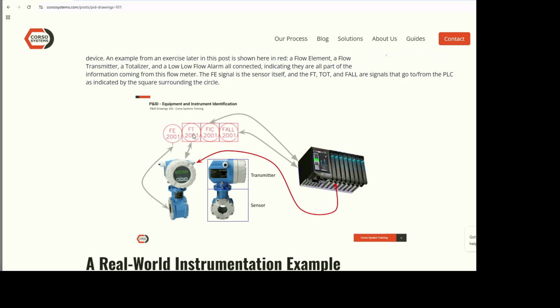And in this case, we would have a tag for our flow value, a tag for our alarm, and we may have a handful of tags for the controller, including a set point, a process variable, a control variable that we're sending to a valve or a pump, and maybe some other things like the proportional, integral, and derivative gain for that control, and any alarm conditions, if it's in auto or manual, etc. So just to read flow, you probably have at least one tag, if not a few, to include alarms. And then if you get into control, you would have additional tags for this flow sensor, and then whatever tags are required for your equipment that's controlling flow.